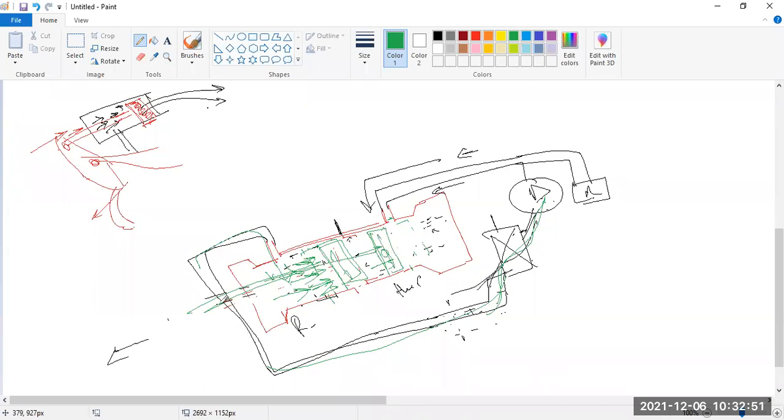In this position it will come, and fluid is entering over here. So the piston will come to this portion. You can see this is the new position of this piston. This fluid will get some pressure, and it will connect to the reservoir. It will go and stay at this reservoir, and due to this pressure the piston is coming to the inner side. Whenever the piston comes to the inner side, the rod also comes to the inner side.